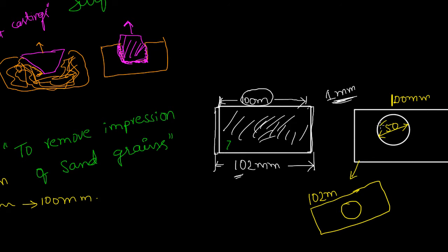We are adding material here also because we put a core inside the mold cavity to get the hollow shape. So that means the core is in contact with the hole. So there must be some sand impression produced on the internal side also. So some internal machining also has to be done. That's why we have to machine the surface. If we have a 50 mm size and we machine that, what will come? A 52 mm hole will come. But I do not intend to get this 52 mm. I want 50 mm only. So to make sure of that, I will give 48 mm only.